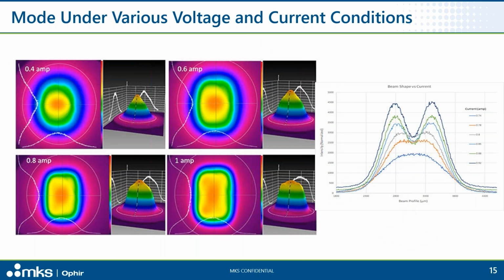Mode structure, including beam size, beam shape, and divergence, is determined by analyzing the beam profile. Camera-based systems can provide high-speed data collection and analysis. Beam profiling applications can be integrated into automated test and measurement environments. These systems provide the spatial performance characteristics of each device under test and permit informed decisions regarding the future of the device. Above, the far field mode is shown. The mode and beam shape changes with drive current. One-dimensional profiles of the spatial beam intensity on the right clearly show how the light output changes with current.